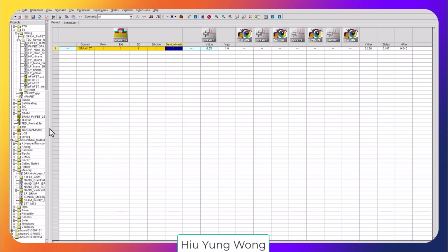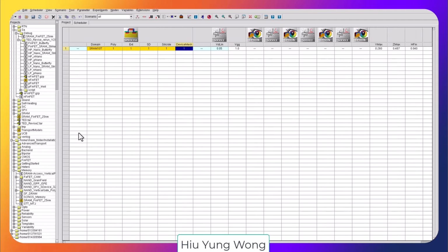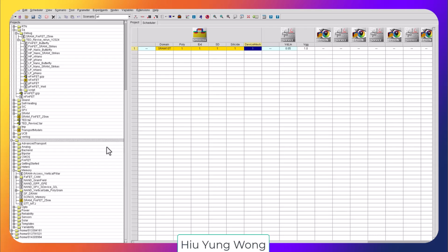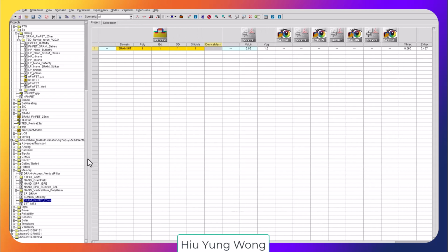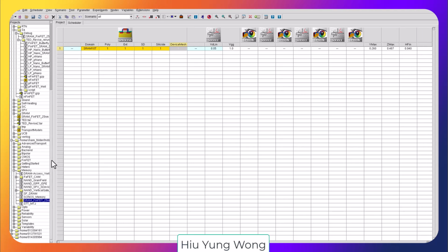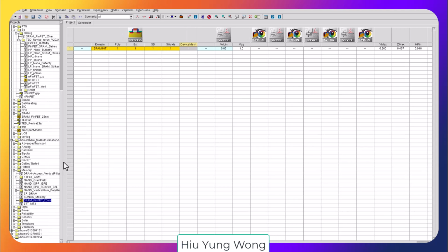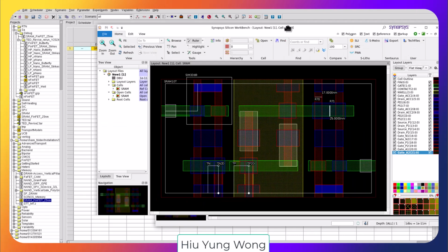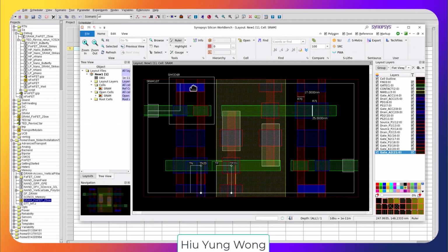to look at this one, right? Look at the example library, but use V release, right? Go to memory and then SRAM FinFET 25 nanometer. Correct. Yeah. Now, so this is just the beginning, right? I want you to play with that, but then we need to modify the layout. I assume you are interested in this. I'm pretty sure that you will be happy and excited to change this layout to the right dimension, make it a smaller cell for advanced technology.